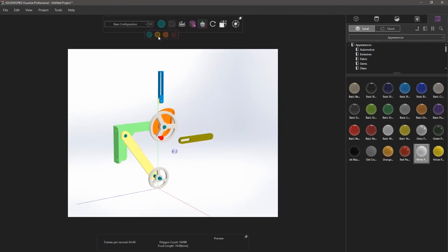There's other things too, like the denoiser tool. So when you're going to render, the denoiser tool also turns off at a certain limit. If the scene is too complex, you won't be able to use the denoiser. So that might make the threshold a little bit lower than you're used to, where if all of a sudden you see the denoiser is not working, you might want to try reducing the polygon count a little bit, and then it may be able to kick back on again with your current hardware. Because that's using the graphics card as well. The graphics card's for rendering, and there's also the denoiser trying to remove all that noise using the same graphics card. So they're kind of over limited resources there.